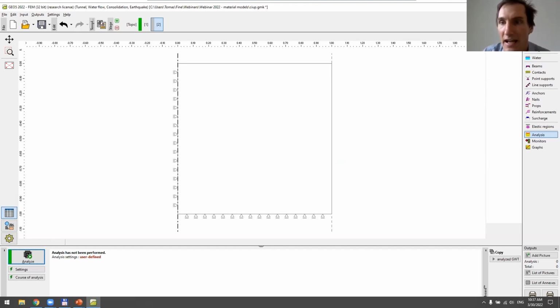And during the undrained triaxial test, we first load the sample by so-called chamber stress, which basically means isotropic consolidation. That first stage is of course a drained problem. So we just prescribe some isotropic stress.